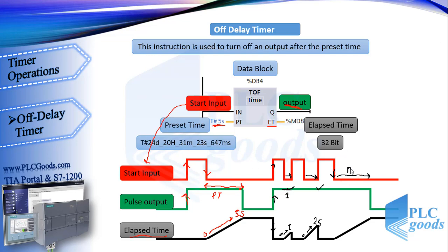OK, this timer turns off its output when the ET output reaches the preset time after the last negative pulse at the start input.